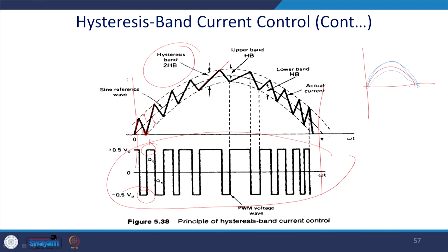So, if it is a proportional band, here you have a space, and here since you have a notch kind of thing, its frequency is required to be higher, and thus control fails, and generally there will be an overshoot or spikes in the case of the zero crossing. That is very frequently observed in students working on the shunt active power filter simulation, because they go for this proportional band hysteresis controller. It is always advisable to go for the constant band PWM hysteresis band.